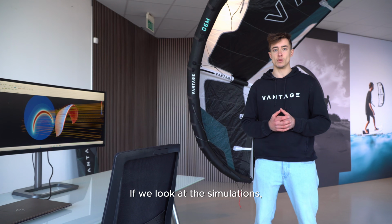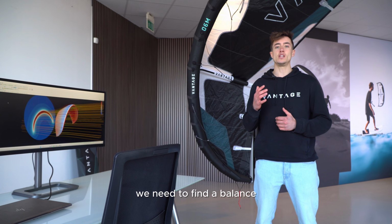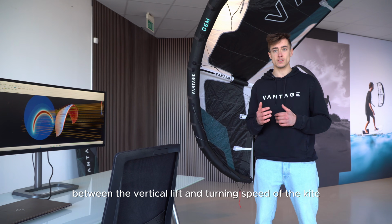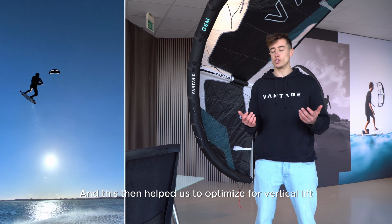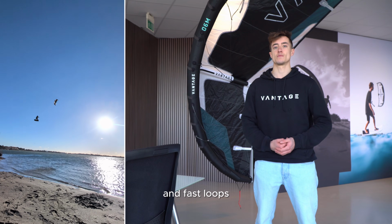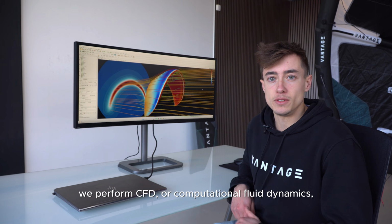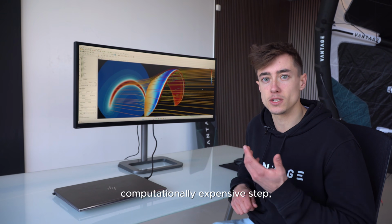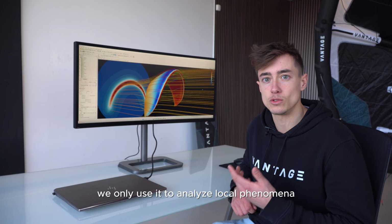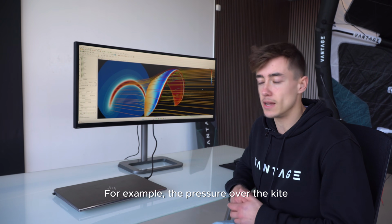If we took a look at the simulations, it gave us the insight and the confirmation that we need to find a balance between the vertical lift and turning speed of the kite. And this helped us then to optimize for vertical lift and fast loops. At the final design step, we perform CFD, or computational fluid dynamics. But because this is a very computational expensive step, we only use it to analyze local phenomena. For example, the pressure over the kite.